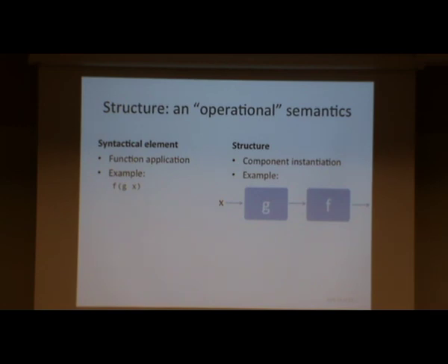This isn't always the case. You have behavioral languages like, I think it was from the 2000s by Mycroft, this language called SAFL. There, if you saw a function application, the function would only be instantiated once as a component, and every time you call it, it will just add more arbitration and bus logic so it can route everything to it. That's not what we do, because we want to get all this fine-grained parallelism that's available in Haskell as easily as possible.